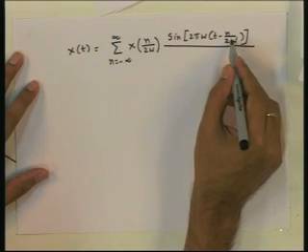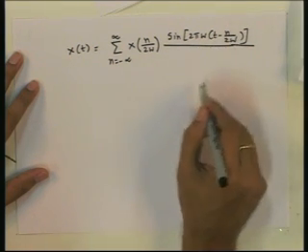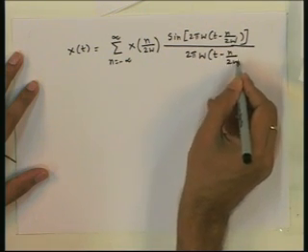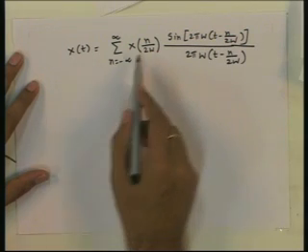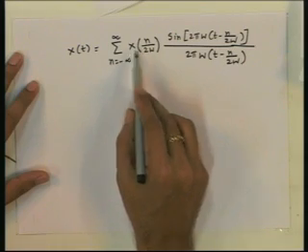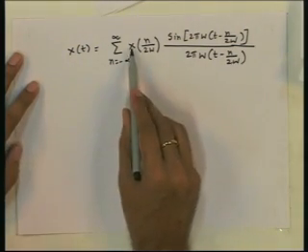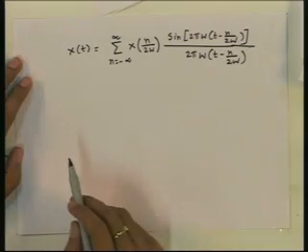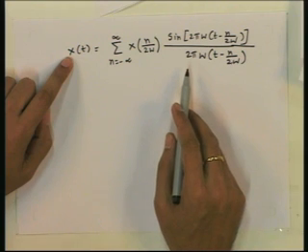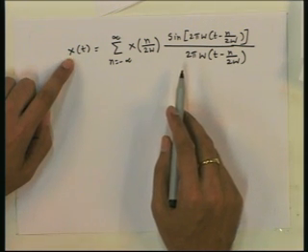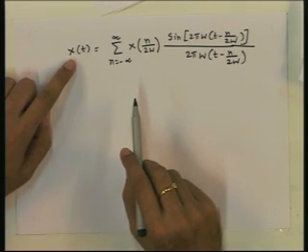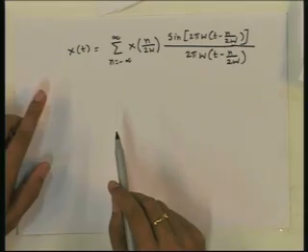Previously, we wrote 1 by 2W as Ts, and 2 pi W (t minus n by 2W). So, where these are independent samples, independent random variables for a stochastic process x(t). So, any band limited stochastic process x(t) can be expressed in this form. In other words, if we sample a band limited stochastic process, we can recover the sample function from the sample values.